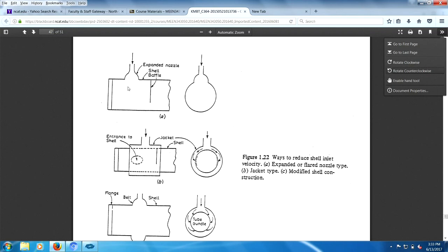Okay, only part of the tubes. The rest of the tubes are not slammed that easily. So I'm very much sensitive to what velocities are coming in to hit my tubes, because that could set up a whole bunch of tube vibrations going on. So a number of things I probably want to do is make sure the expansion bellows is large enough to let the flow in. You can have a belt.